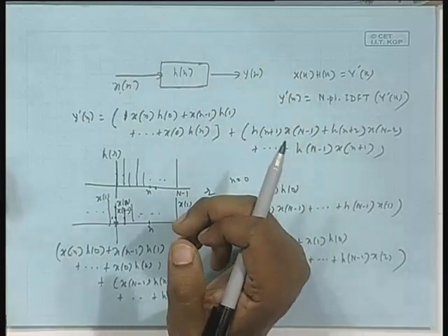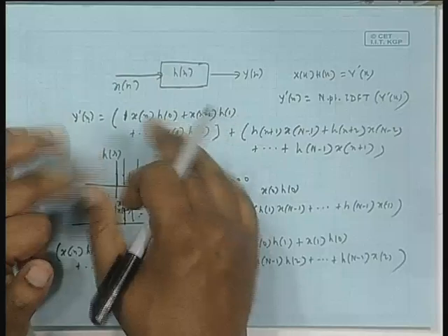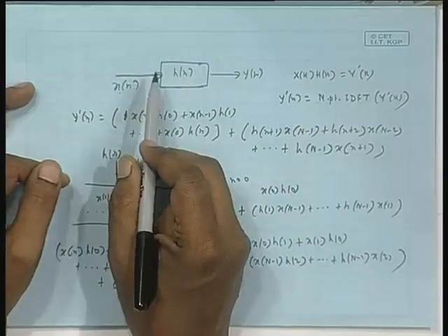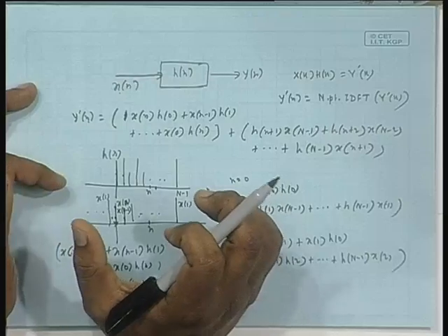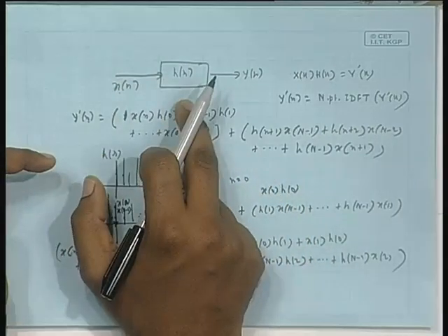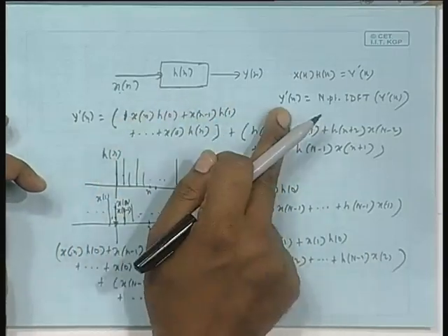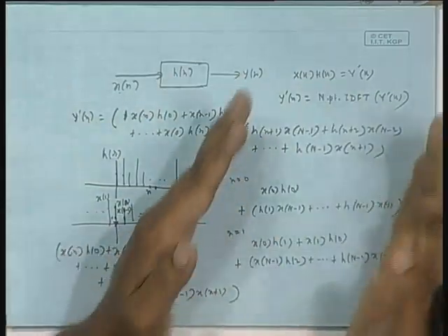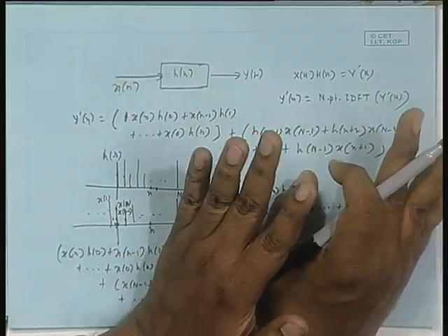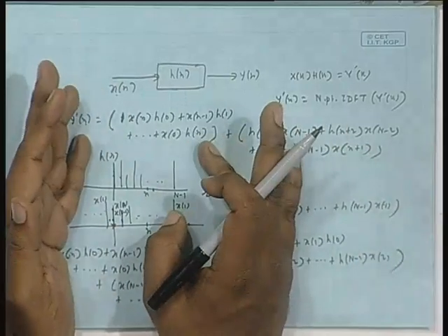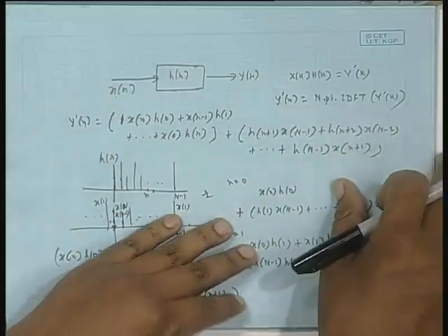So, all are of the same range, but the question is, if I carry out the DFT, the IDFT means how many point DFT? N plus M minus 1, the current length, you call it capital L. So, L point DFT, L point DFT, multiply, L point inverse DFT. If I do, I get an L point sequence. Is it the linear convolution? If I carry out the graphical method, will this error disappear? That is the thing we have to verify. If this disappears, wonderful, then that will indeed give us linear convolution only. So, this we need to verify.